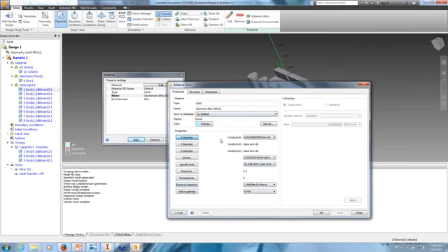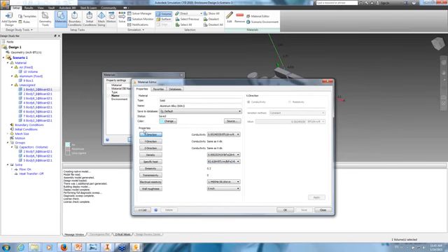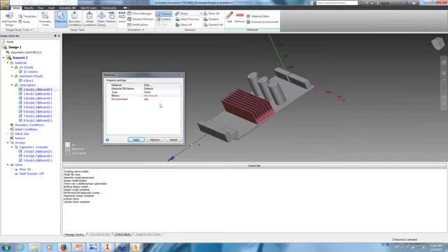These are the materials that are built into this material, the aluminum 6061. If you want to create your own, you can give it a name, and you can save it to your materials. You can type in whatever values that you want, and then apply and save, and it will save it to your own material library, so you can go back and pick it. You don't have to enter numbers every time. This is the case for any kind of material.